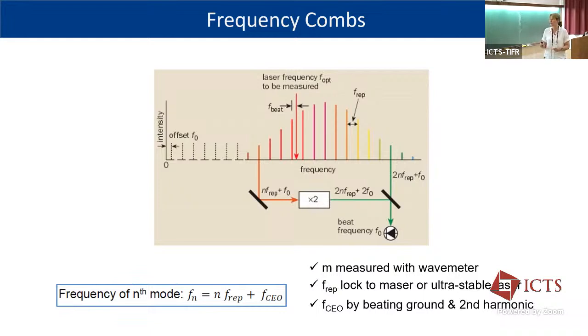Because it's still multiplied by the M, you see. If you do the error propagation, the M is on the order of 10 to the 5. So this levers it to the optical, but the M is just a number. It doesn't have an error, it doesn't have a dither. So the dither is only here at the microwave frequency.